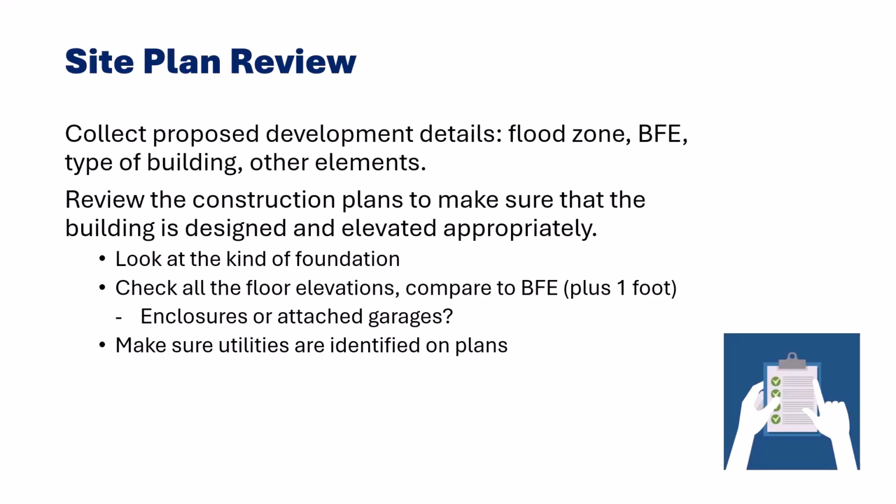If the bottom floor is below that elevation, then check that it has everything it needs to have in terms of flood openings, being unfinished space, and meeting those limited uses. That's why it's important to make sure that utilities are also identified on plans. Their location and elevation information might impact what a building's lowest floor is.